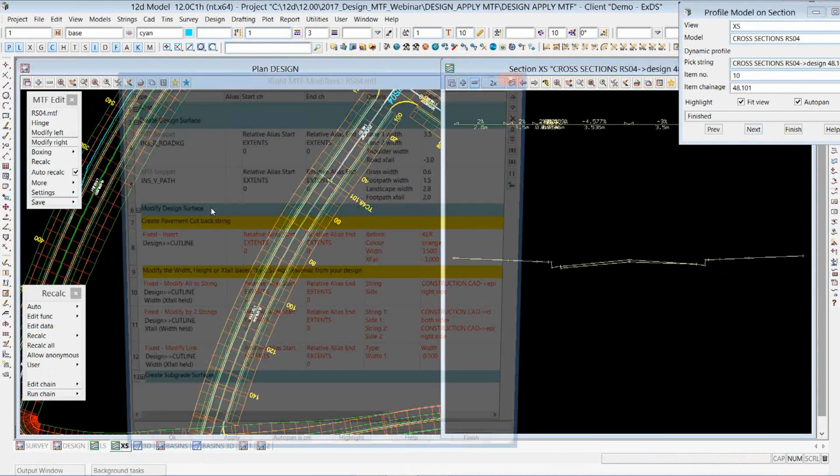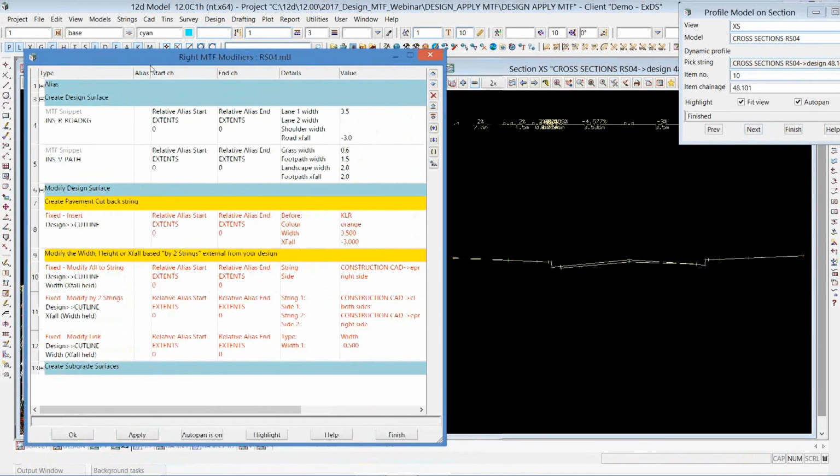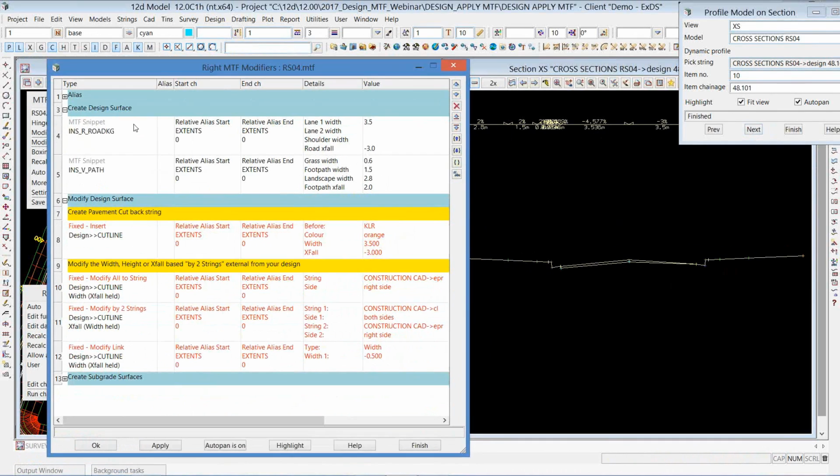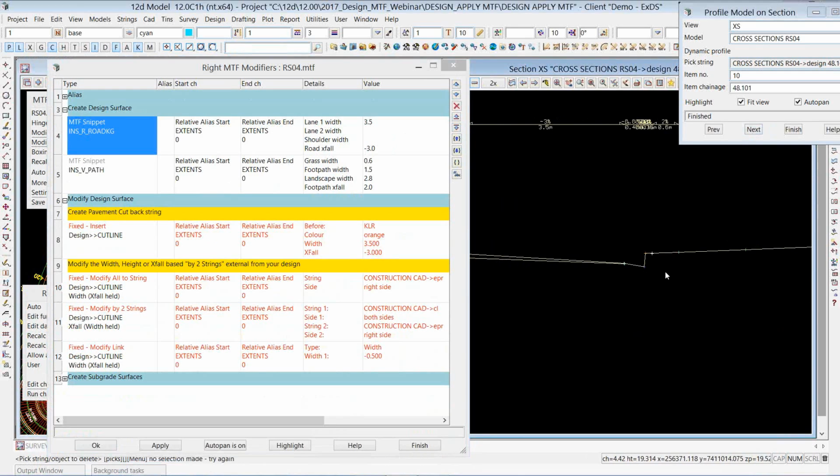The right side, set up again, a lot of questions we get asked by designers and local council authorities. We're basically putting a road in, they put a standard snippet in, standard dimensions and things like that, but they aren't going to construct the whole thing. They only want to construct maybe from 300 or 500 mils back in from the existing edge here, and they're just going to build the lip of the curb out to the footpath and just amend this side of the road and update the curb and gutter. So how do we put a cutback line in?